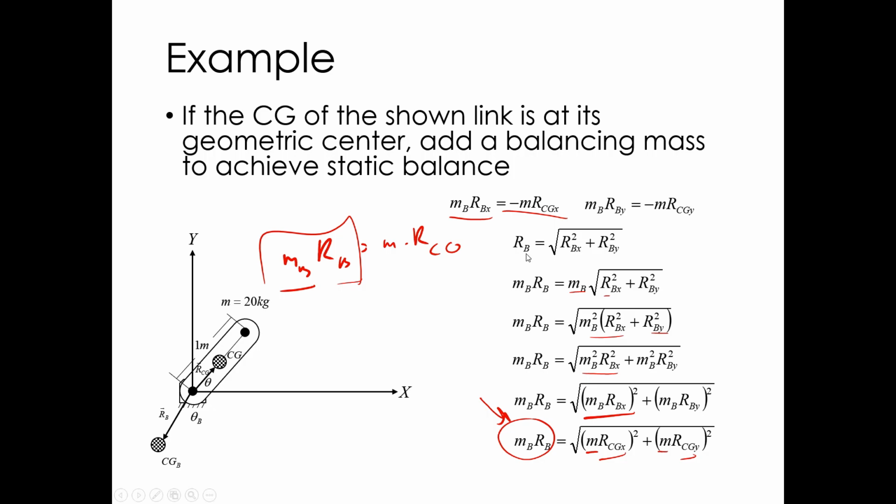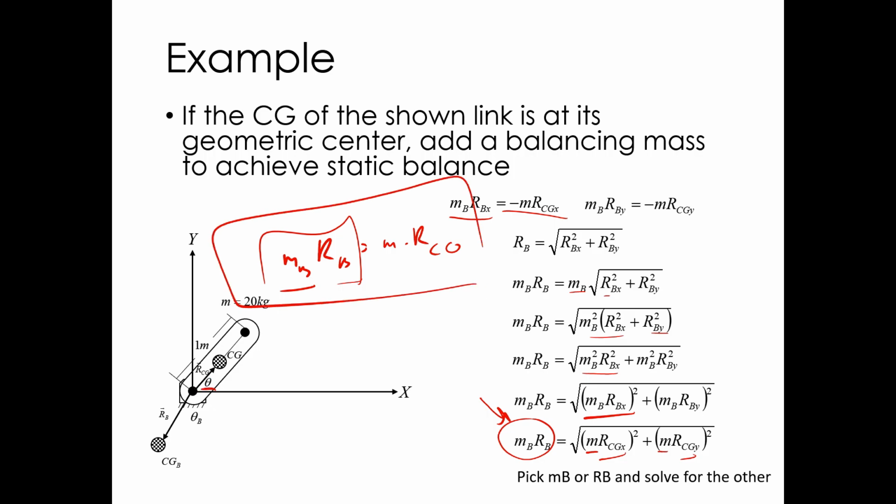So there's choices, so I can use a lighter weight farther away, or a closer weight, or a heavier weight closer. Again, you can go through and use these equations, but it's easiest to just find theta at 180 degrees and then use mb/rb, mass of the balancing weight times the radius of the balancing weight, from the origin to where the balancing weight is at. That has to be mass of the thing I'm trying to balance times the distance it is away from the axis. And as long as you know those two basic things, the angle and the magnitude, you can balance anything statically, and you don't have to go through all of these equations to do it.